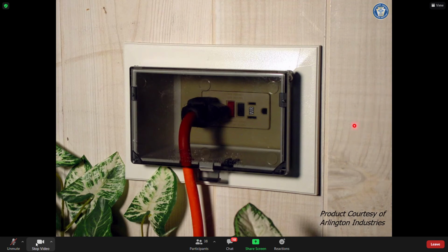The listing has to be on the receptacle itself. Correct. But the WR indication is not required to be there. The manufacturers are just doing you a favor by doing that. Same with TR for tamper resistant. They're not required to put TR on there, but they do.